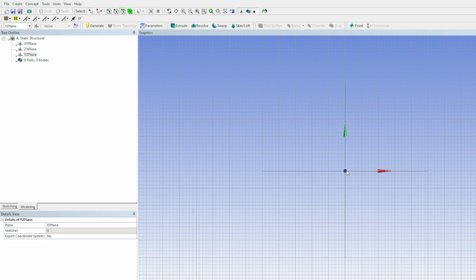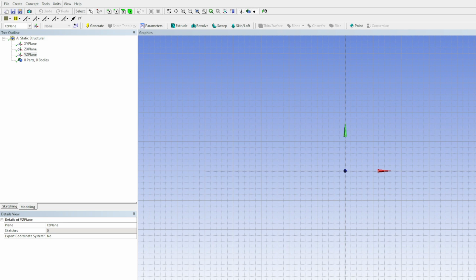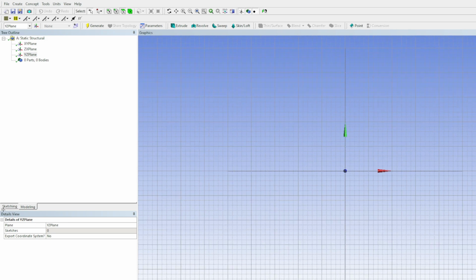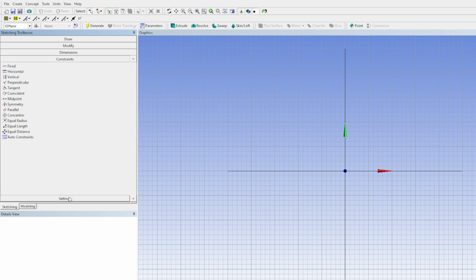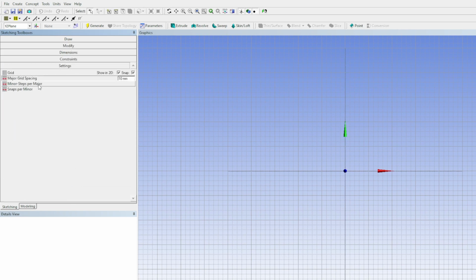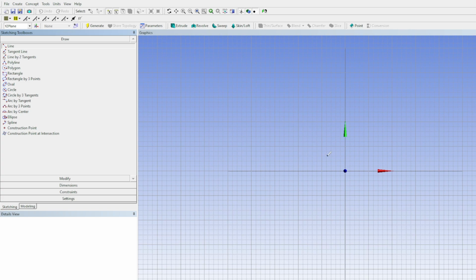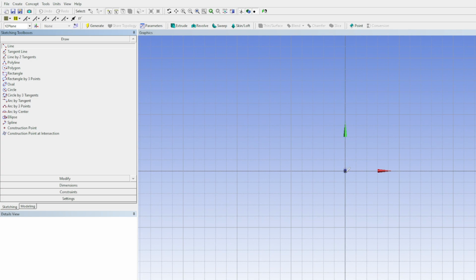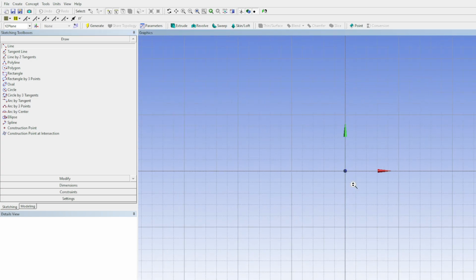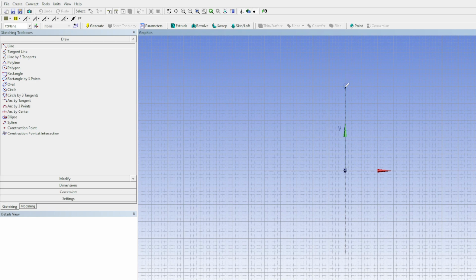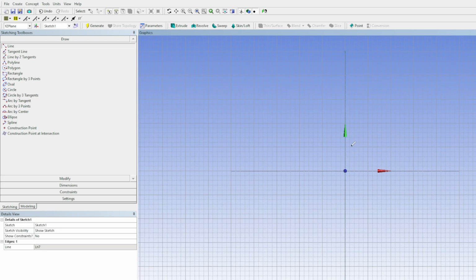So then I go ahead and hit this sketch view option that kind of lines it up this way. And then we're going to change our units to millimeter. We're going to go over to sketching, settings, make sure that grid's turned on. I just have 10 and 5 as a default. But now we're going to go to the line tool, and from the origin here, which sometimes it doesn't like to actually snap to. There we go. Just bring this line up here, and on this one we're going to sketch up a certain distance and then over a certain distance.